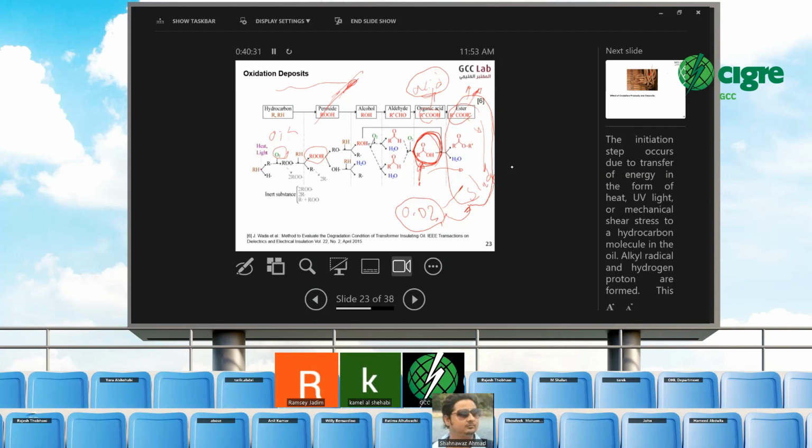Okay. Keep monitoring the trends of these gases. If you see an increase, then most probably you have a discharge inside this cable box. You have to find from where the discharge is coming. If you have a testing tap on those bushings, check the testing tap as well. The cap of the testing tap, if it is open or loose, check it.